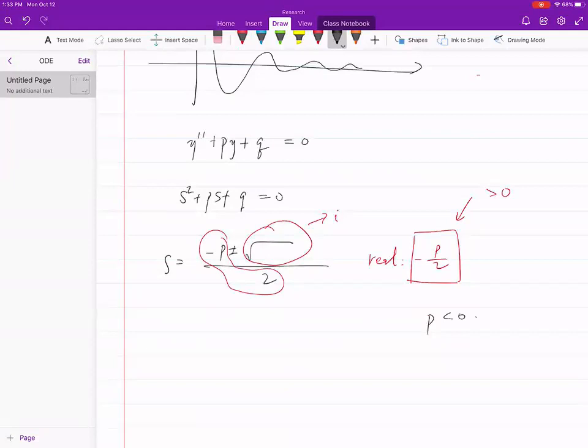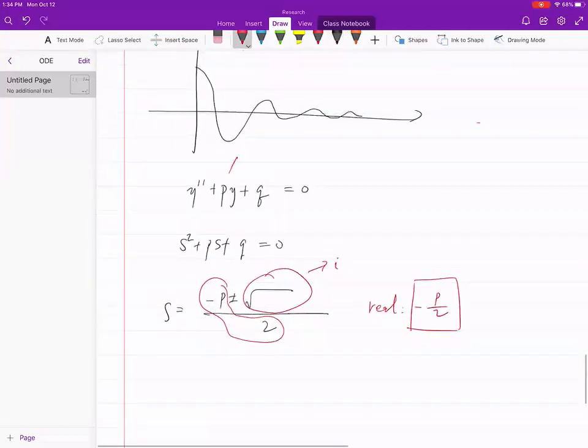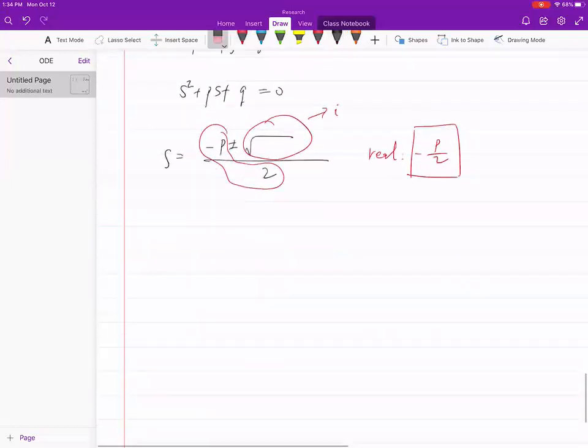That's why if you have friction, it never gets amplified. The reason is because the sign of P is always positive. That's how we got the friction. So it's always damped. Even mathematically, you can put a negative number for P, but in real life, P is always positive. Damped, because P is always bigger than 0. Then you can think about other cases. Maybe P can be positive or negative, but that cannot correspond to a spring mass damped oscillator. You need to have something else. It can't be friction, because friction always slows you down.